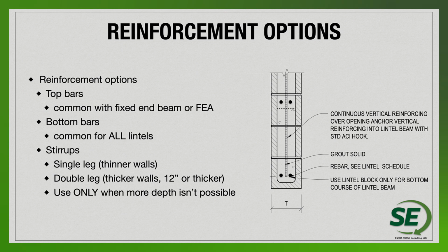Lastly, we can consider stirrups if we have a limited depth element, making sure that we consider the ability to add stirrups to increase the overall shear capacity. You could have a single leg or double leg, but only when more depth isn't an option.